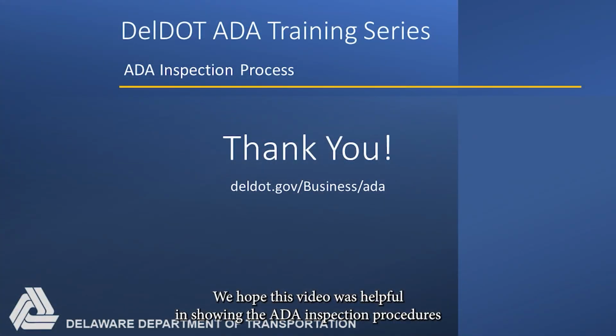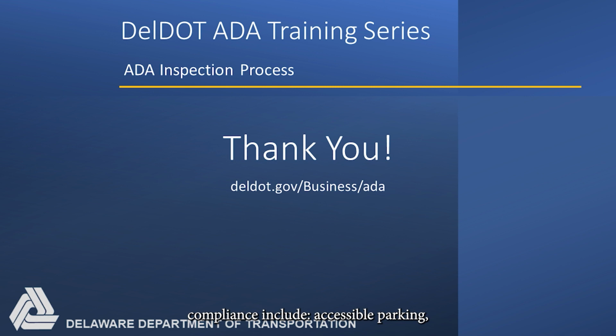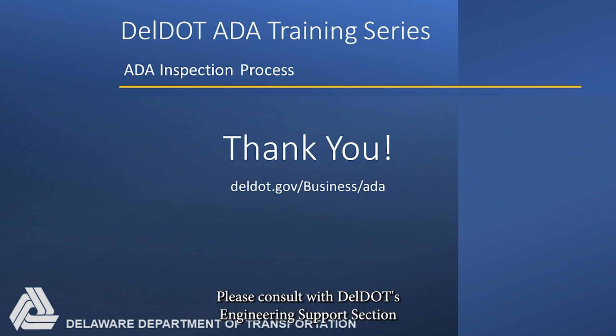We hope this video was helpful in showing the ADA inspection procedures for common pedestrian features found in DelDOT rights-of-way. Other features that may be encountered and will need to be inspected for ADA compliance include accessible parking, pedestrian overpasses and underpasses, signs, street furniture, passenger loading zones, and doors, doorways, and gates. Please consult with DelDOT's Engineering Support section for guidance on ADA inspections.